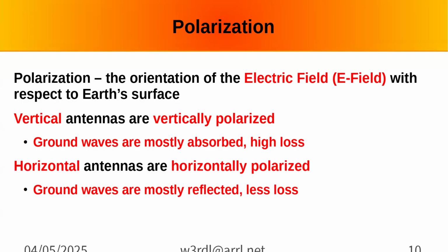And ground wave is just a reflection that comes back at a certain point. It's additive to your signal. They combine at some point in the far field. Are they in phase? No, but at a certain point they will be, because the path length is different. When we talk about Yagis, it's a similar thing. That's what all those elements are doing. They're at different phases and spacing. So at certain points, they all wind up in phase with the original signal.